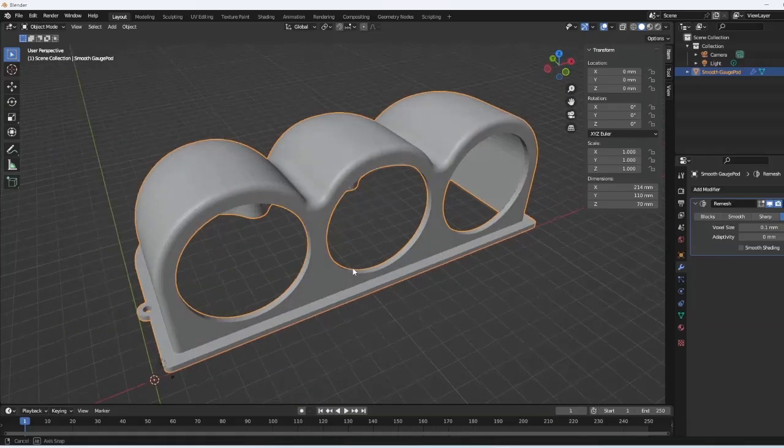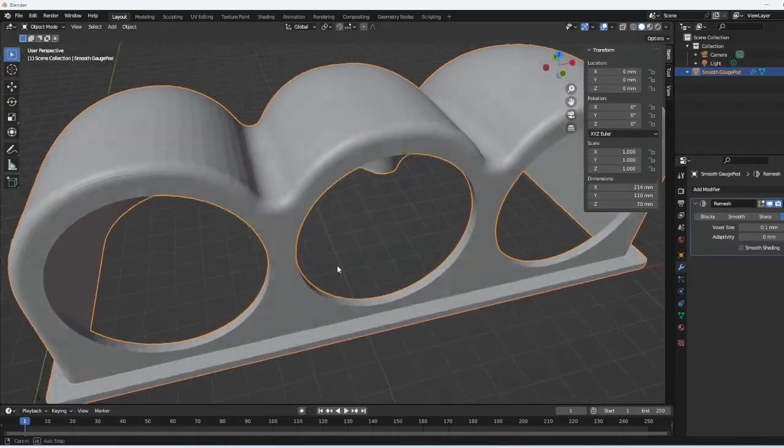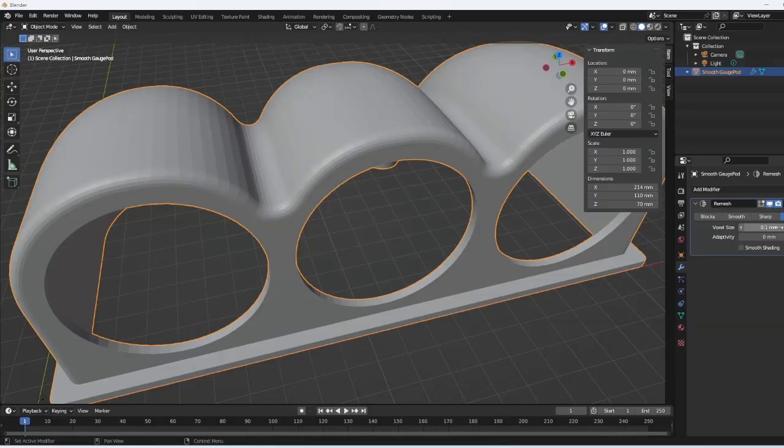So in this particular case, you can see, or it's hard to see actually the results, but you've got this voxel size, and that is the size of how big each of these nodes are, like how long those points are. And you saw before that we had a really long one on the side of this part, but 0.1 millimeters is quite small. I don't want to kill my computer yet and make it think too much, but I'm going to go to 0.5 millimeters as the size.